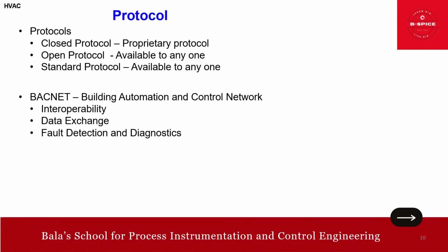Then we have fault detection and diagnostics. We call it FDD. It helps in energy usage and determines potential faults before they cause significant problems. Then we have remote access and control. With proper security measures, users can monitor HVAC devices and parameters from a remote location. Then, of course, we also use it for energy management, friends. This is about the protocol, and especially BACnet.